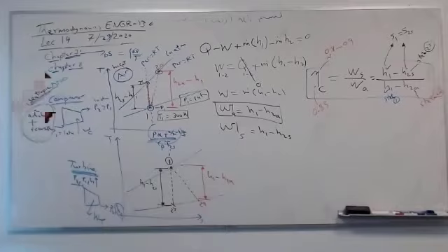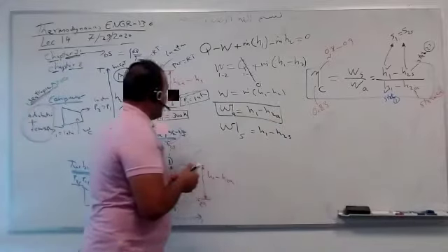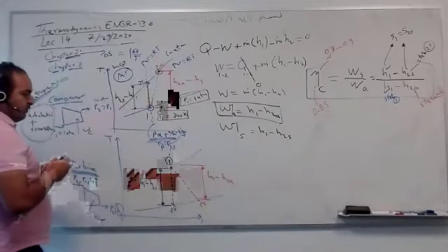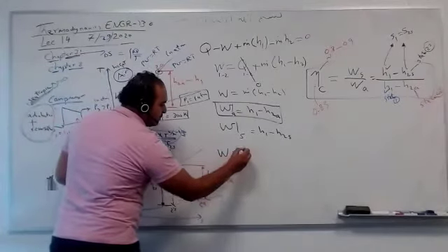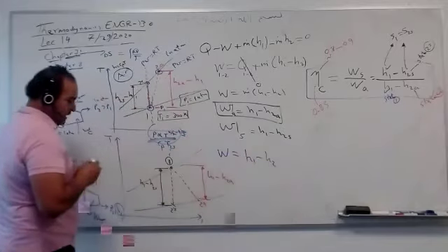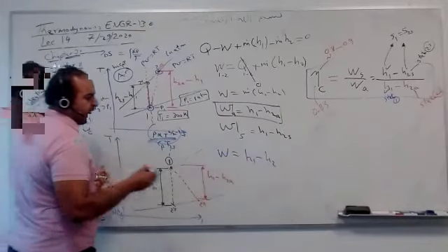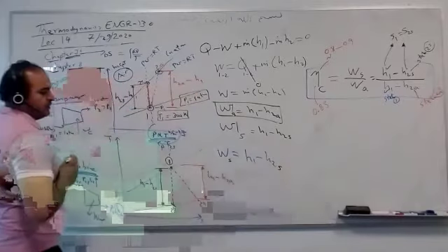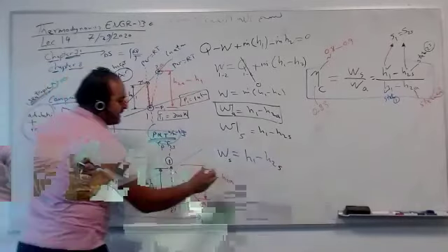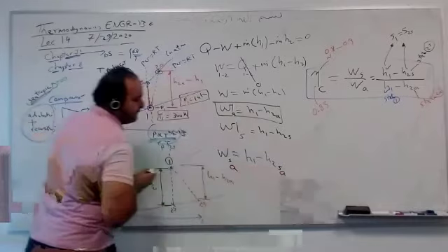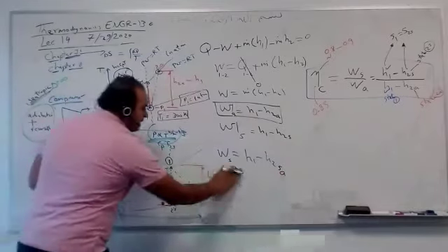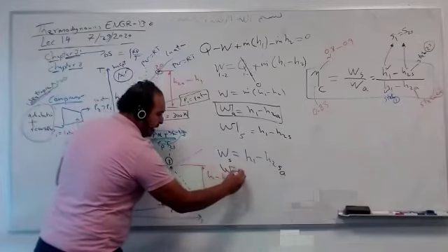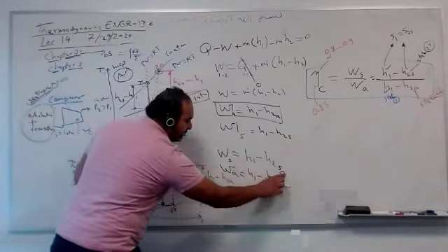So what happened, guys, here? I get less. But the good news is the efficiency of the turbine is much higher than the compressor, much better. So we can use the same way. If you apply the first law of thermodynamics for an open system, we find W is just H1 minus H2. If H2 was H2S, this would be S, reversible. Everything is adiabatic. If it's A, it would be A. So WA equals H1 minus H2A.